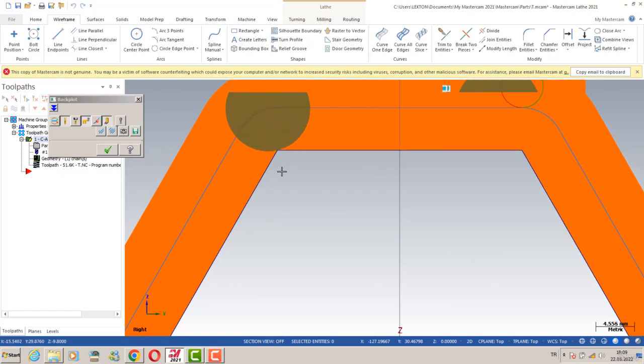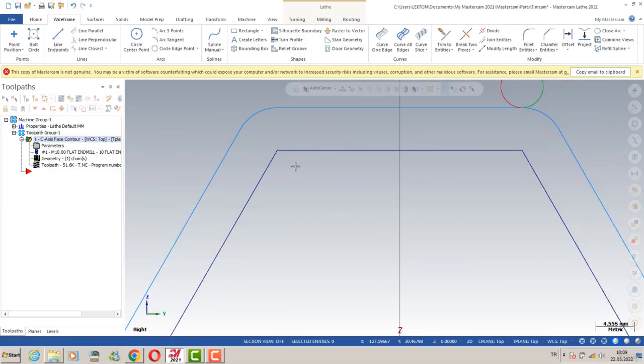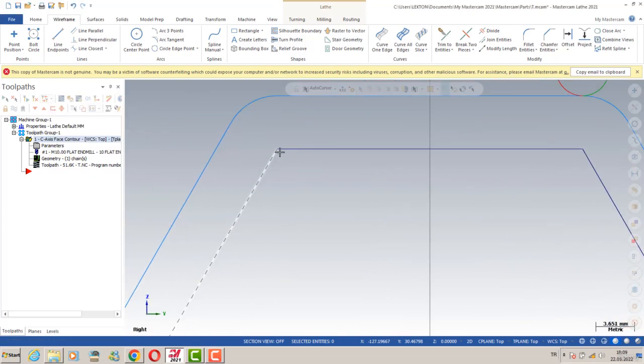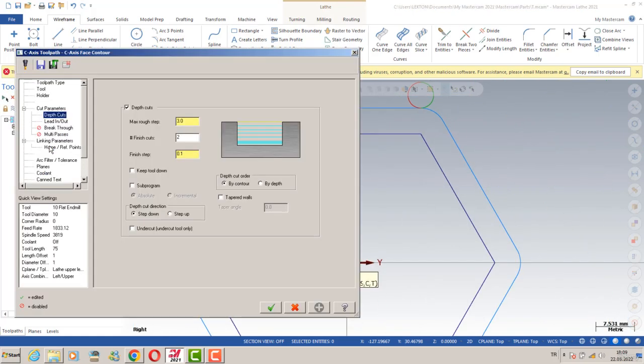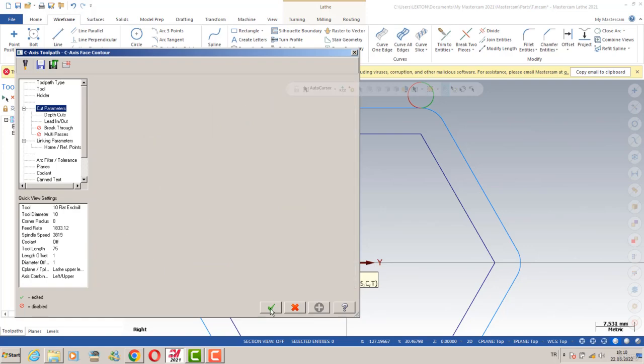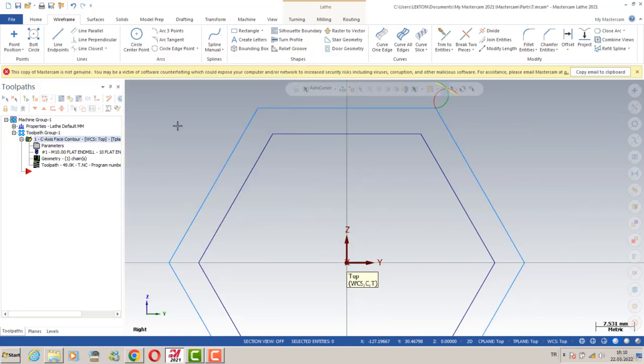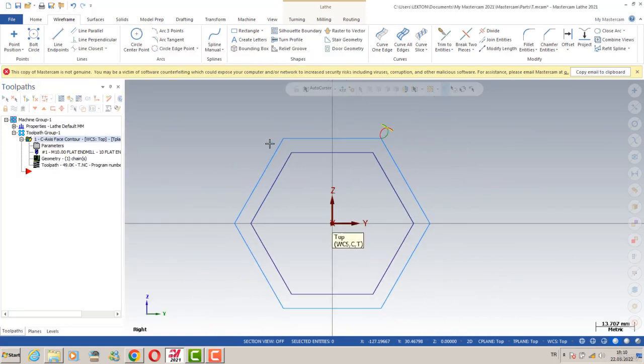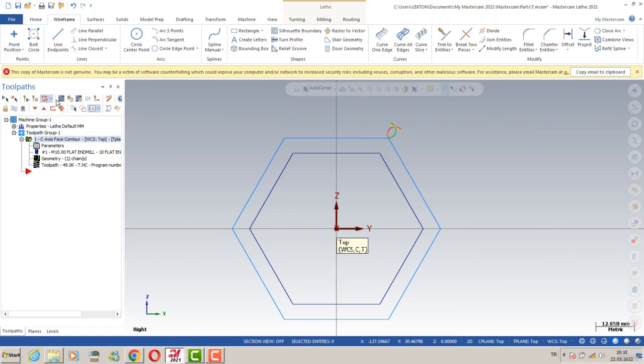But if you see some runout on your tool, of course you can maybe see an undersharp or not sharp corner here. If you would like to be sure about that, you can turn to cut parameters and organize it here. This is the sharp options, and we can use the none option here. If I select the none option, we can see that kind of toolpath here.